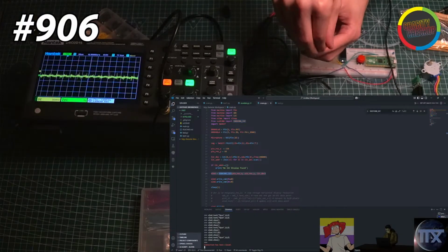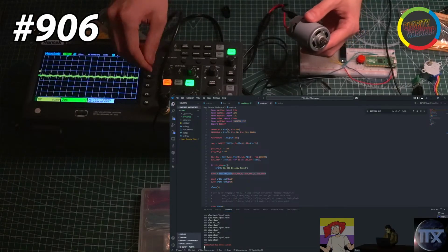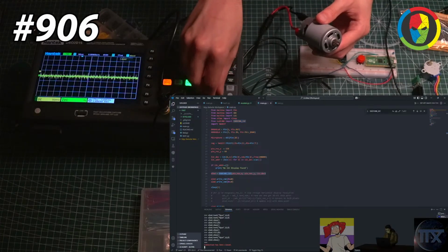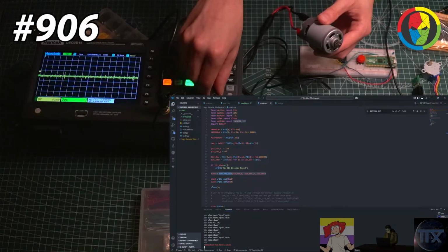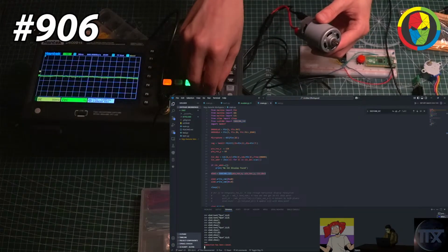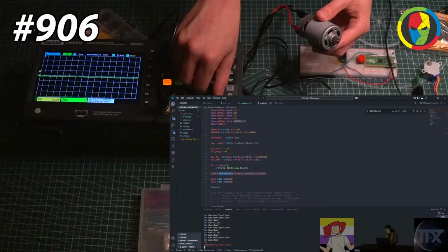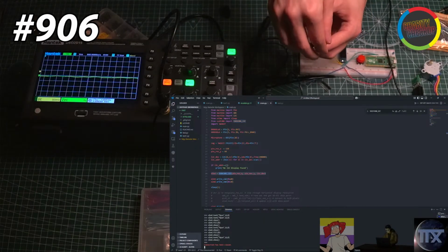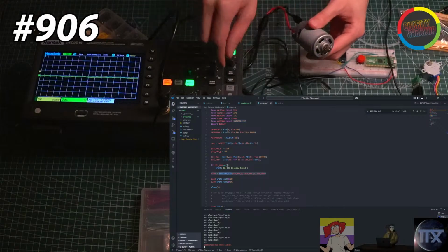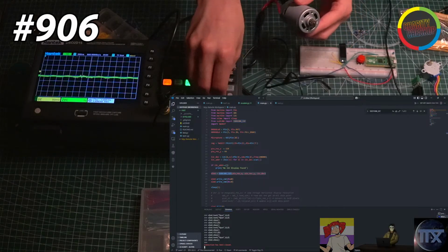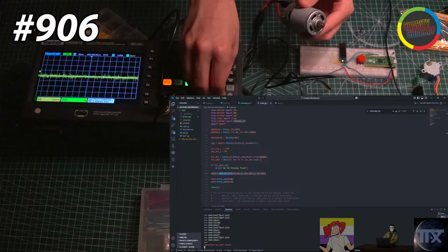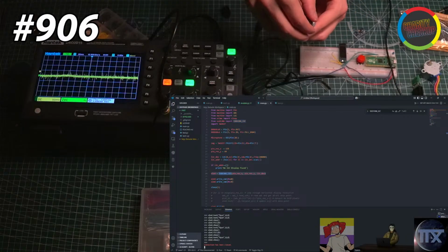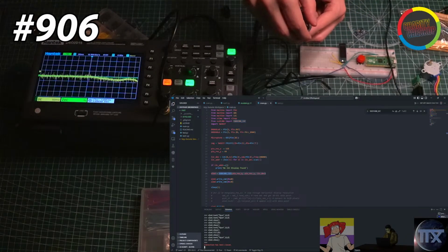Yeah, you have to zoom way out in time. So zoom out time-wise, so that the trace across the screen is super slow. And that will be the last column. The other way, you're zooming in. If you want to zoom out, so that way, I didn't realize. Yeah. Okay. 5 microseconds. Okay. 20. Yeah, zoom all the way out till it's so slow.